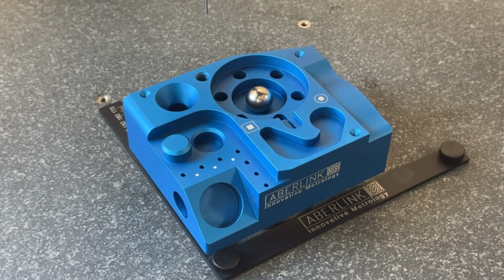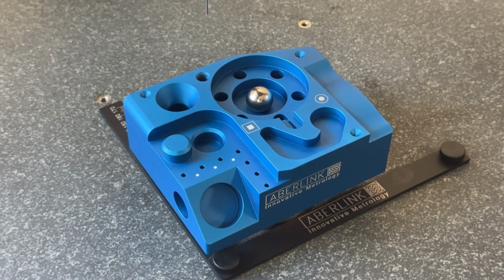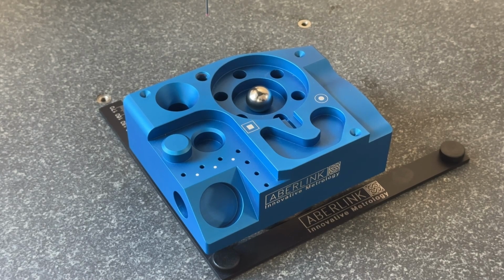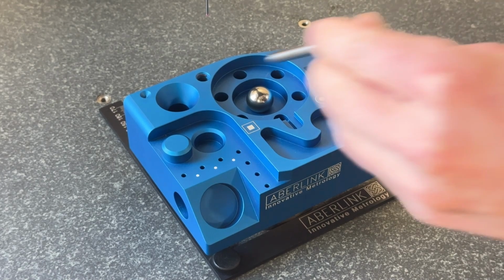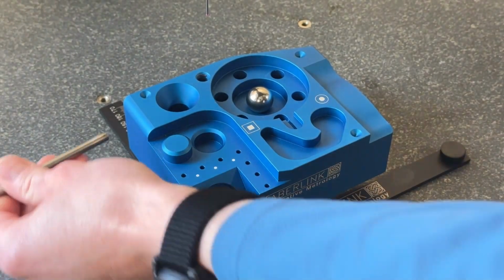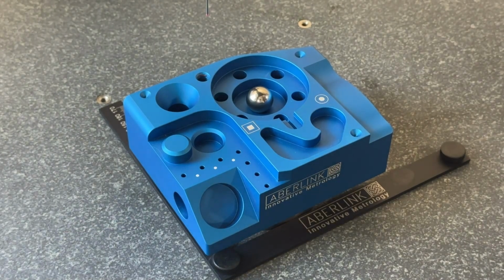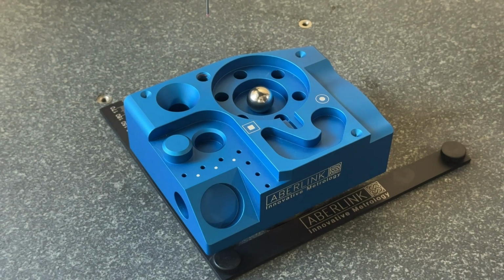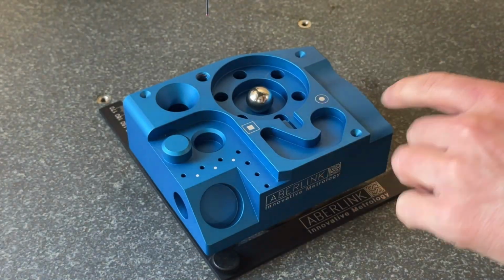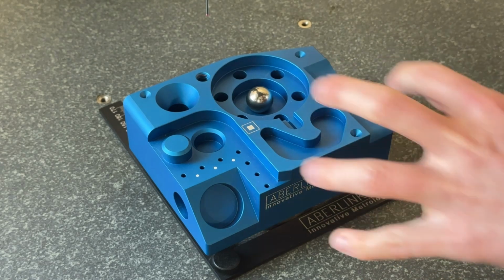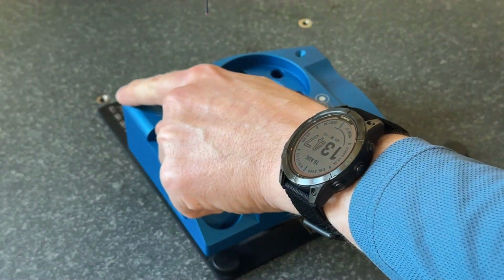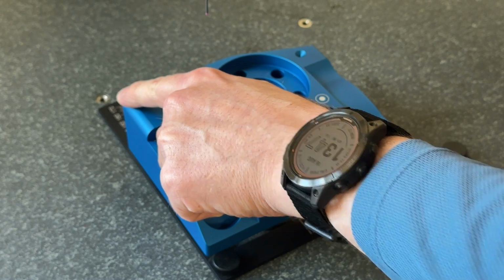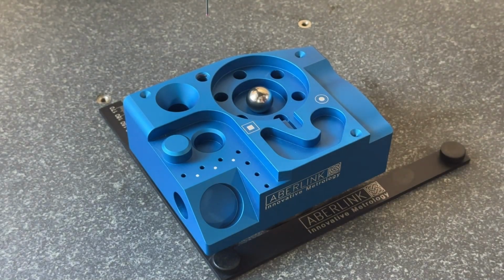So in this second example, we are going to link the position of some circular planes to a datum frame rather than the reference system. So in this example, the reference system is the plane on the top, that's datum A, a line along the left hand side, which is datum B, and an intersection point at the corner, which is datum C. So anything we measure as standard now, the template of where to go and measure the feature will be linked to that coordinate system. So that will be our XYZ 0, and that makes a huge difference on things like